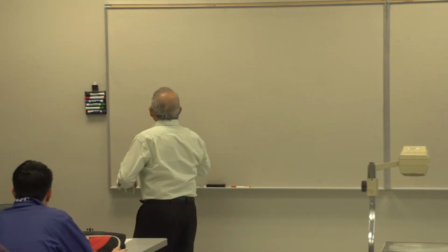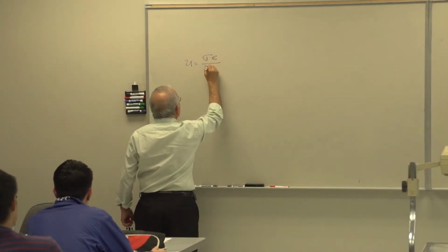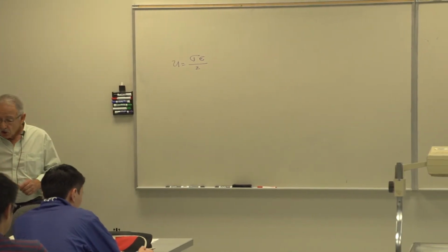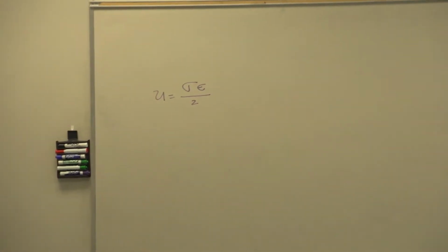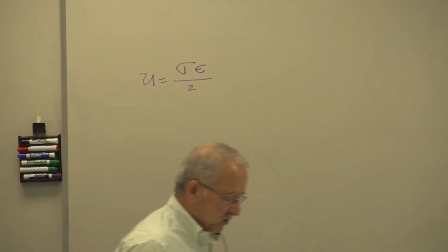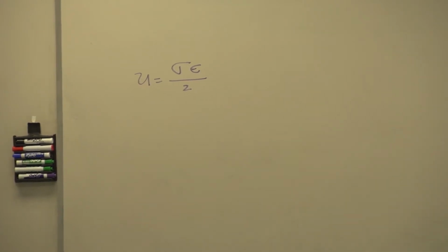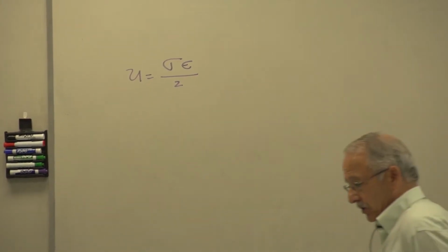This equation. That's strain energy in the material. Whenever the strain energy in the material at the location of high stress, maximum strain energy density in the material, reaches that at yield in a simple tension test, the material will have failed. This is the total strain energy in the material.